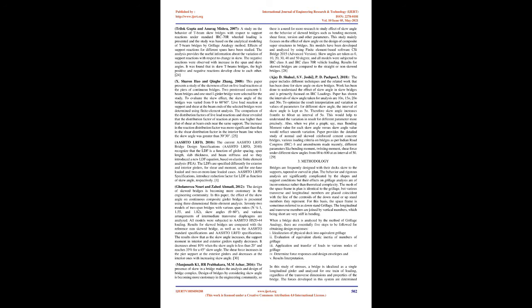Bakht, 1988, examined that those methods of bridge analysis that are developed basically for right bridges are also sometimes used for analyzing skew bridges, provided that the angle of skew is less than 20 degrees. It is proposed that bridges having S tan θ / L less than 0.05 can be analyzed as equivalent right bridges, where S, L and θ are the girder spacing, bridge span, and angle of skew, respectively.